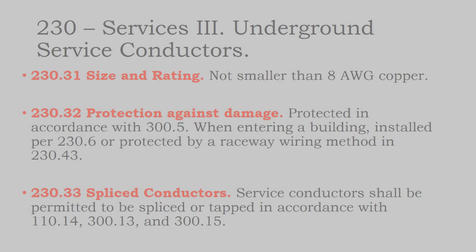So there's the grounding system that needs to be permanently spliced. When you're running your bare copper wire up to the rooftop to land on the solar arrays and ground it, you may want to run another section of ground off to another subarray. The only way to take two pieces of copper and put them together and consider them permanently connected is to use a crimping tool that is hard as heck to use because it's so large.